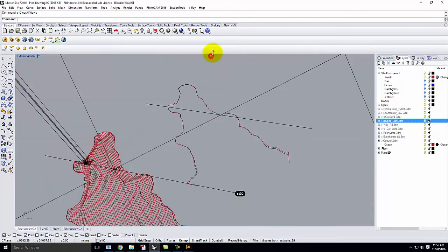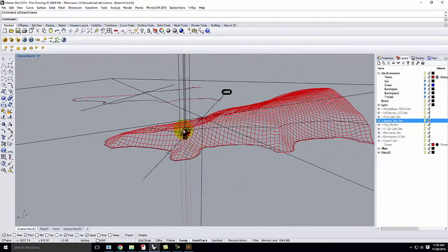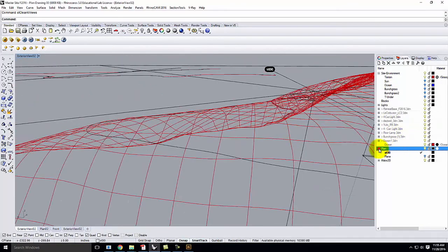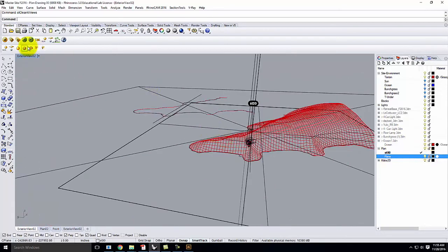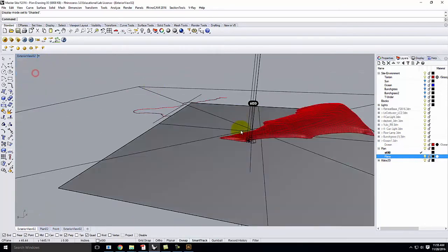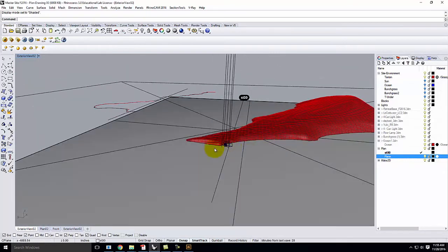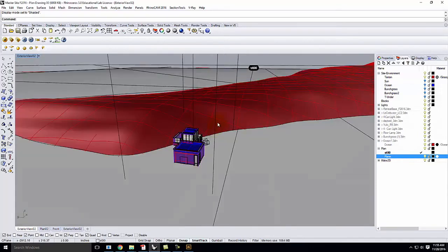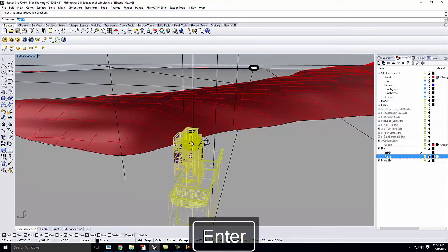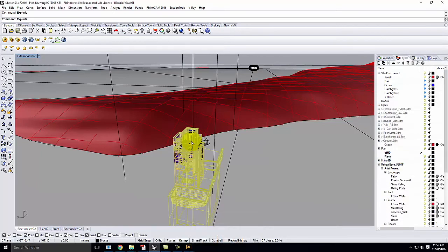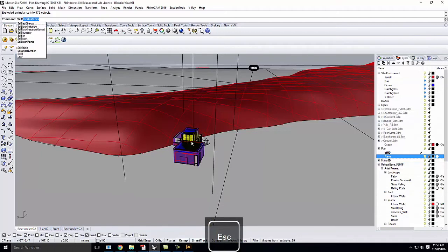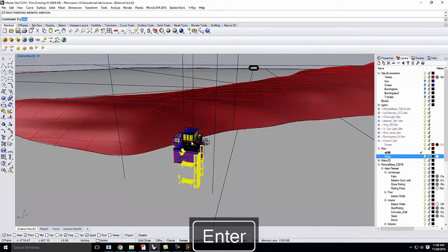And with our normal setup, I'm going to turn back on that big plane that I created in the beginning. And let's look at this as a shaded mode. There it is. And I'm going to go ahead and split all of these objects. But before I do that, let me go ahead and select SEL block instance. So I have the block instance, and I'm going to explode. Remember, when I do this process, it breaks apart everything. Okay, so let me SEL block instance again. Those are the windows. We're going to explode them.